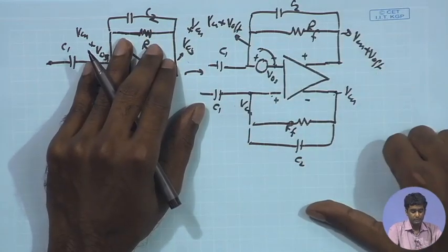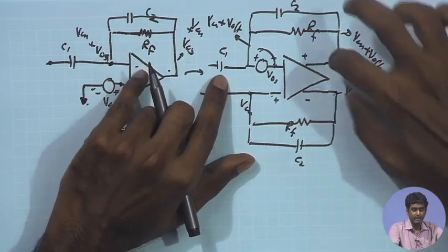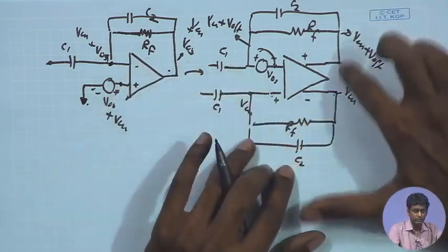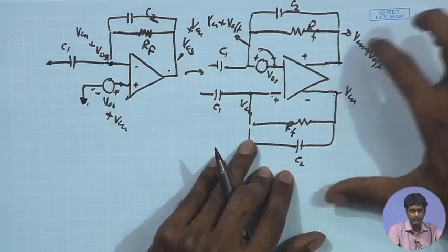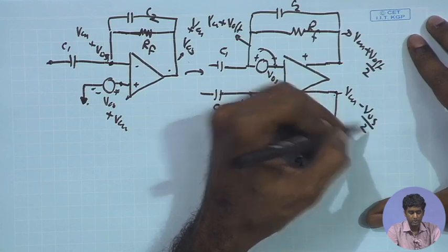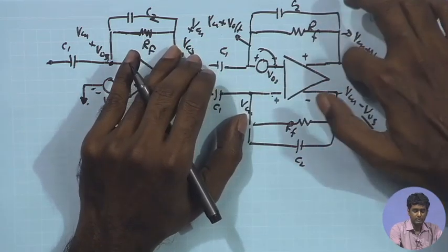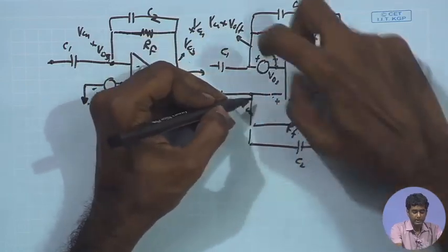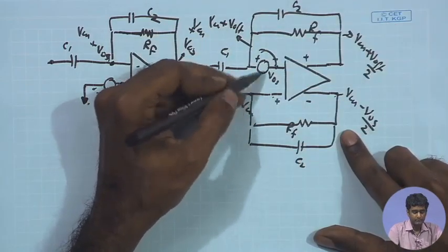And effectively, if I have common mode feedback available, it will make sure that the common mode voltage is the same, and therefore it will push it to V offset by 2 and minus V offset by 2, so there will be a differential swing, and in that case I can model the V offset also as plus minus V offset by 2 on these two terminals.